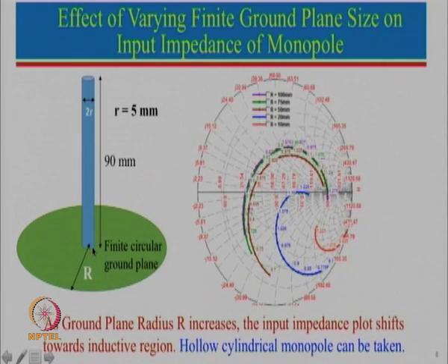So the results I am going to show you are all for the monopole antenna kept at the center of the circular ground plane here. But suppose it is put over here, or here, or over here, then the results will change. So results will change if the location is changing. And suppose it is a rectangular ground plane of a smaller width and a larger length, then again the placement of the monopole antenna plays a very important role, and one really has to properly simulate these cases.